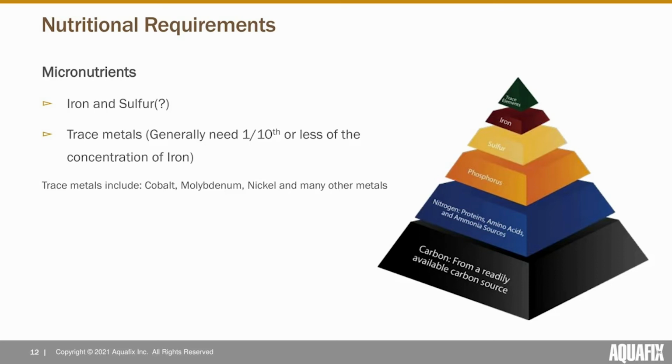All right, so we have a quick question. Is it best to consider an ideal C to N ratio in the influent rather than the COD to N to P ratio mentioned here? And so when I am mentioning it here, I am primarily looking at the COD to N to P ratio in the sludge feed. It's always nice to do analysis both for the influent and in the digester, especially in cases where you have variable loading, because unless you have a really good representative composite from your influent, you can be missing something like a metal that comes in at certain times but not other times, and it will sit in the digester long enough to have a contributing effect.